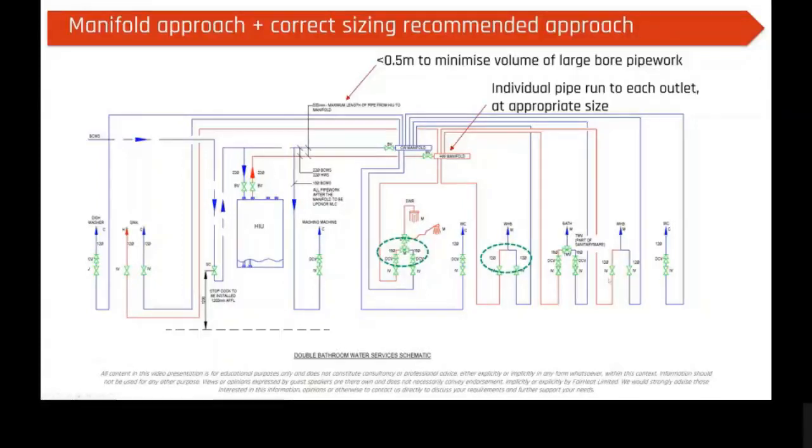That's a small bore pipe, and that's what's needed to get decent delivery times to a low flow rate application. And then we're running to our shower in a 16 mil, which is a high flow rate application, but our kitchen sink again is only receiving a 12 mil pipe. So that's the kind of approach we're going to need to start seeing to hit 45 degrees in 45 seconds across the board.